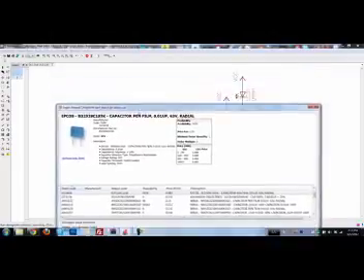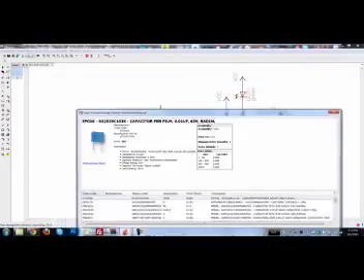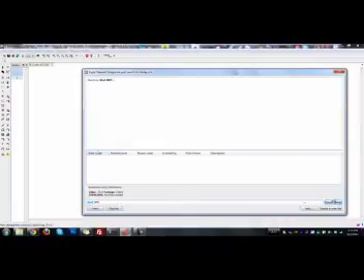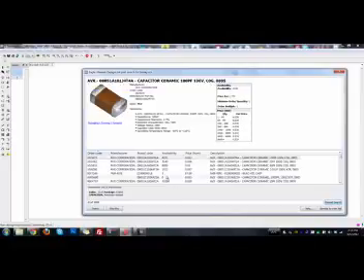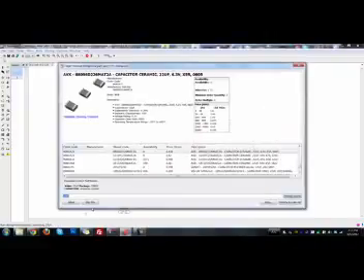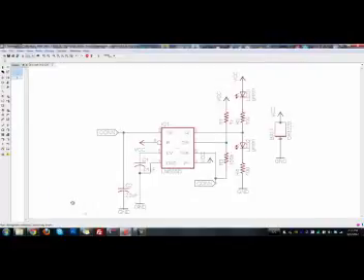And the capacitors, so for example, the first thing it looked up is 0.01 microfarads. Now we know we're using an 0805 capacitor, so let's give it a little bit more information. Hit search. Okay, and that looks a little bit more reasonable. That's a 0.01 microfarad capacitor, 0805, looks fine. So we can select this and it'll add it to our bill of materials. The next thing it looked for is 22 microfarad. It found 22 microfarad 0805 capacitors. These are perfect. We'll hit select.